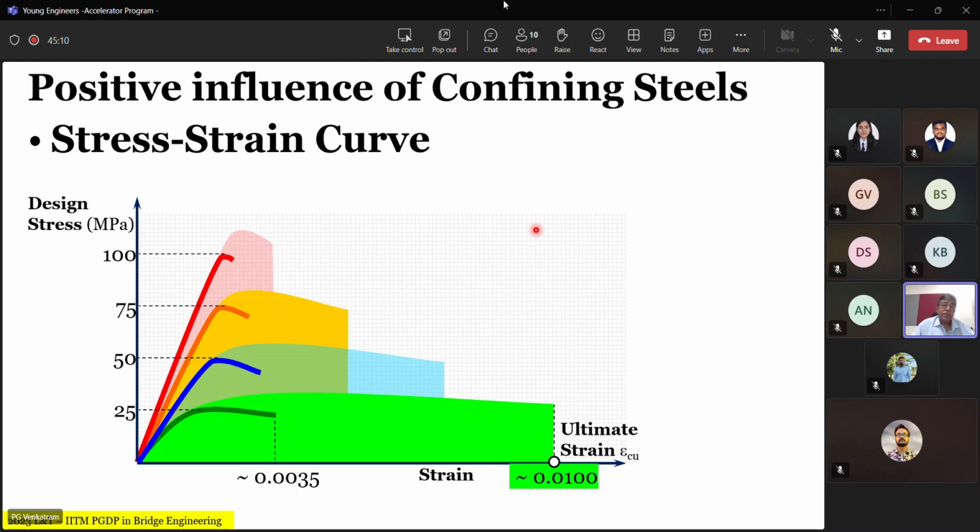You notice what is happening to the internal concrete ductility as the concrete grade increases, even in spite of confinement. Remember, this green graph is with confinement effect, the original curve is unconfined. So the green, the blue, the orange and the pink are all confined concrete. The impact on the loss of the ultimate strain is tremendous as you increase the grade of concrete. So what does this tell you? That you shall, as far as possible, not use very high strength concrete. So please do not buy into the idea that high strength concrete is great. Don't buy into that argument at all.